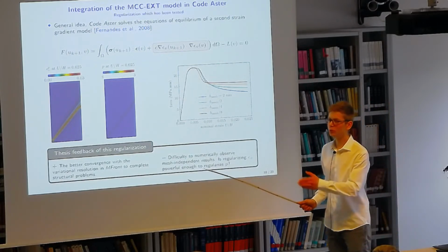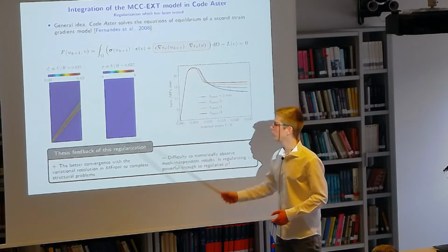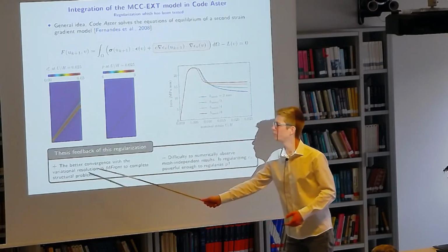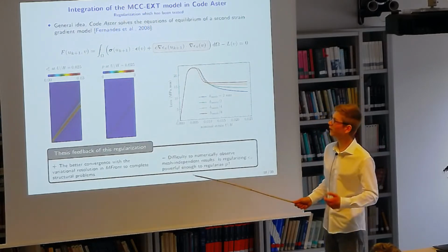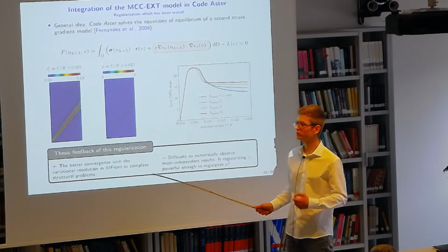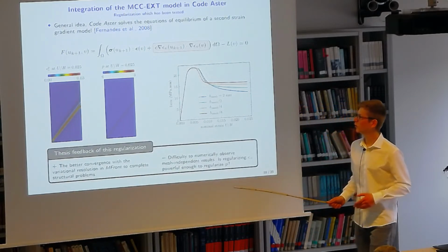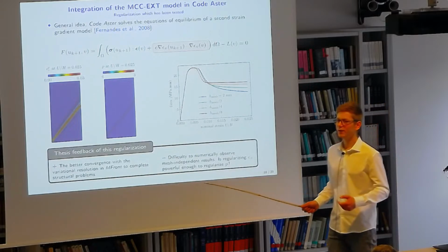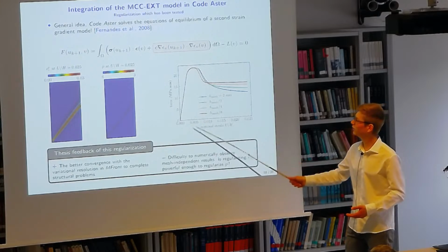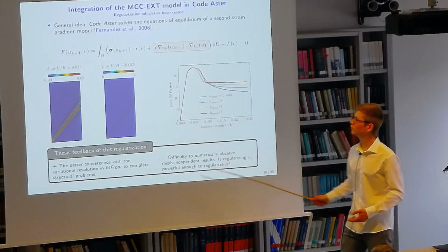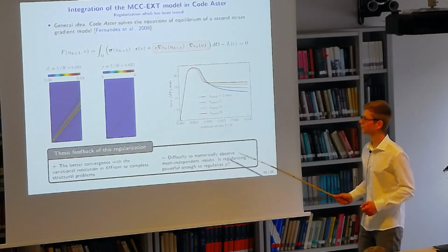However, using this approach, we were quite mixed. On the one hand, for sure, it helped, with also the use of a variational resolution to update the internal variables, to get calculations to the end, even in the presence of localization and softening. However, on the other hand, we were quite disappointed in obtaining mesh-independent results, as is illustrated here with the evolution of the force with the displacement on a biaxial compression, even with the refinement of the mesh size.